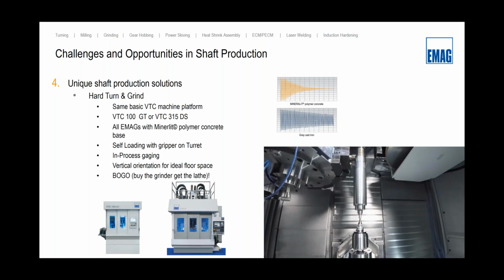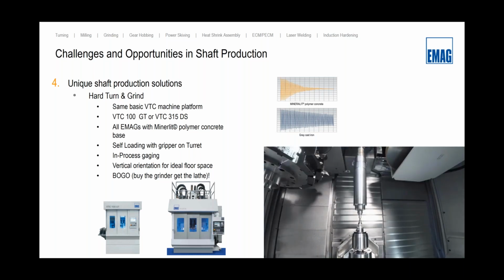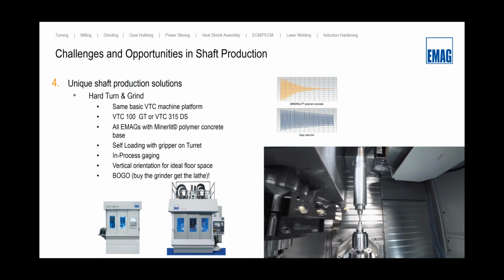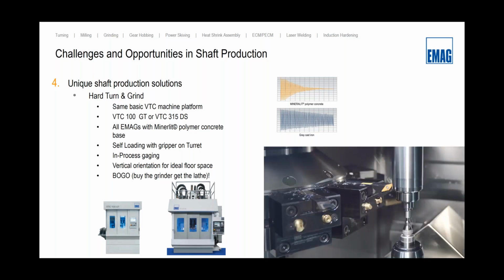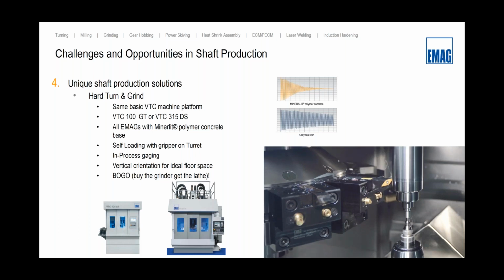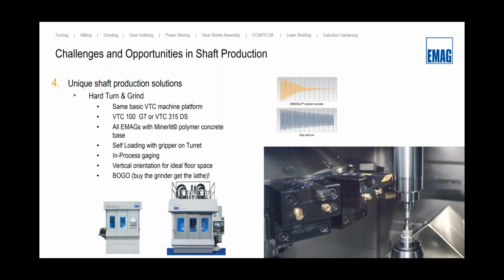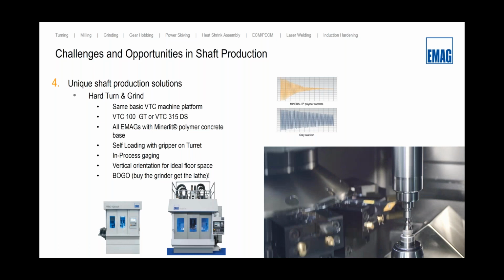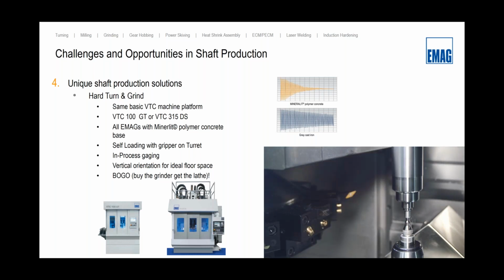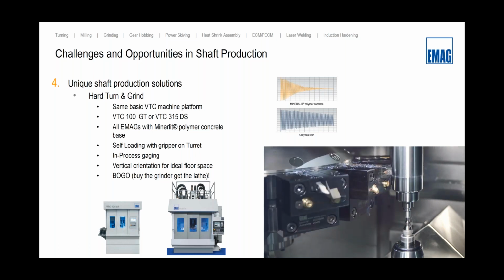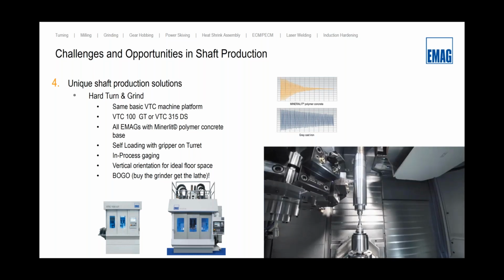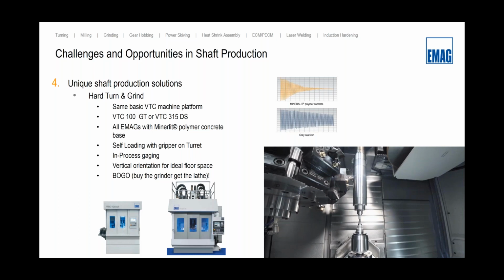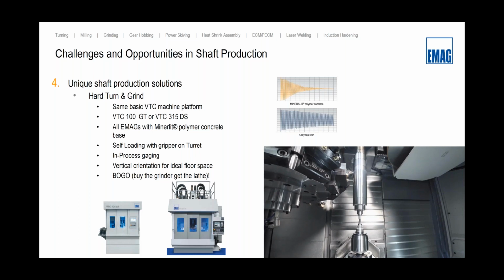With this cast granite machine bed, that gives us less vibration than a gray cast iron or a welded steel base. And when you have less vibration, your tool life is better on the turning side. You also have less heat buildup, which is critical on the finish side where you have tighter tolerances. You basically have a big rock as your machine bed, so less fluctuation, better vibration. You ultimately get better quality.